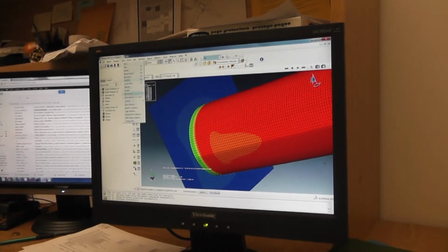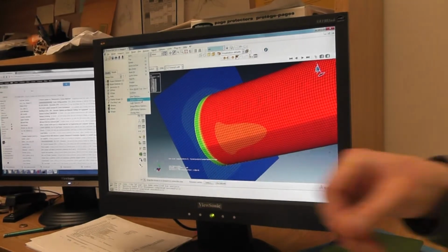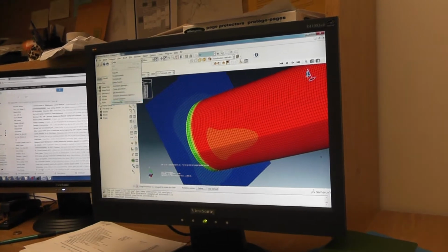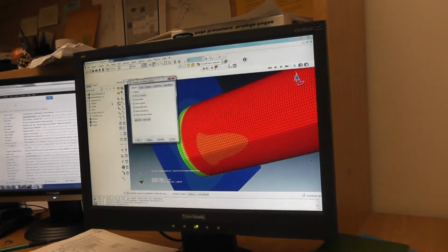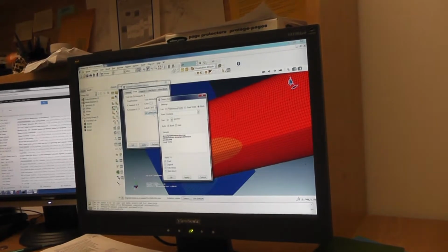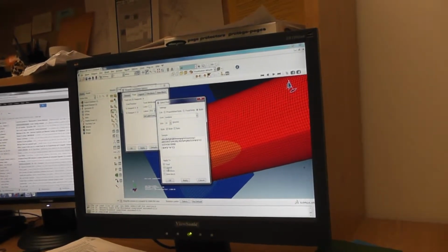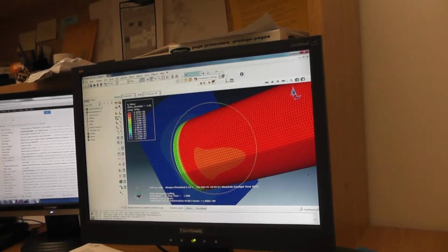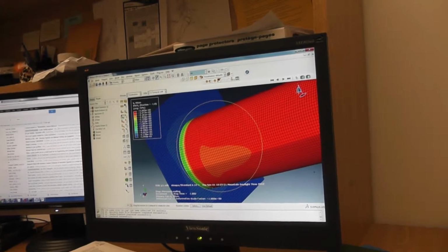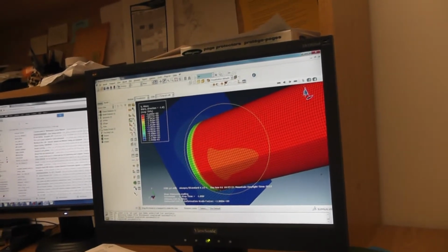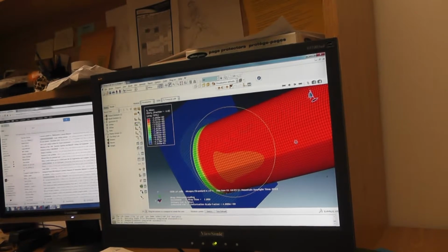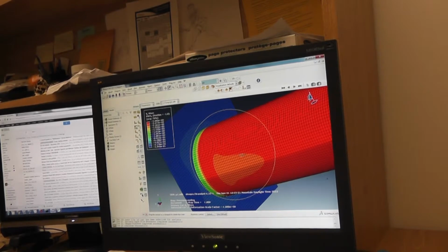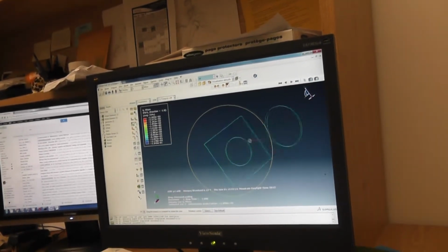I'm going to look at view. So here we don't have any stresses, right? This green part. No, we'll see view options. Viewport annotation option. Font. Let's make it 14 for all these. So the green, yeah, we actually have less stresses in the green. That's correct. The maximum stress is about 260, around here. Everywhere. Yeah, everywhere. That's right. Okay, so this is what we expect.